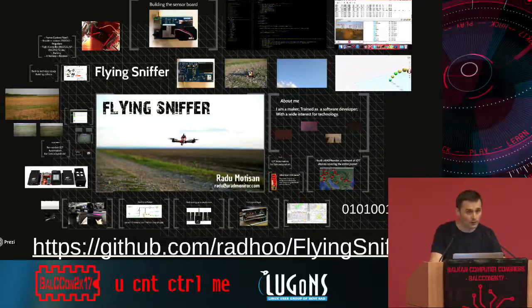For data communication, I've been involved with some deployments using LoRaWAN technology, and that is exactly what you said, low power and very wide area networks. And they use something like a few tens, hundreds of bytes per second at the most. So they are very low bandwidth, and they also use very low power, and the applications for those include things running on batteries for years.